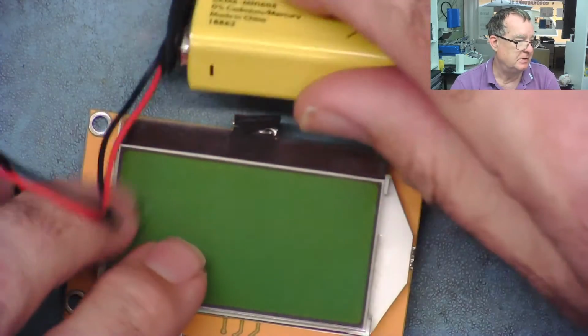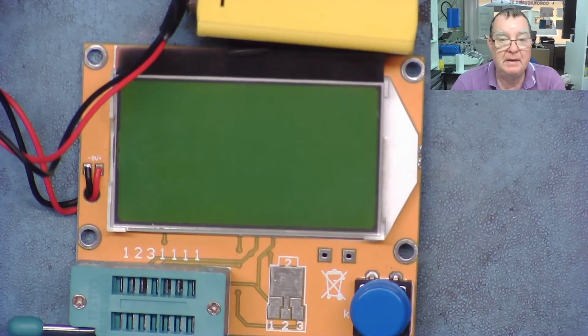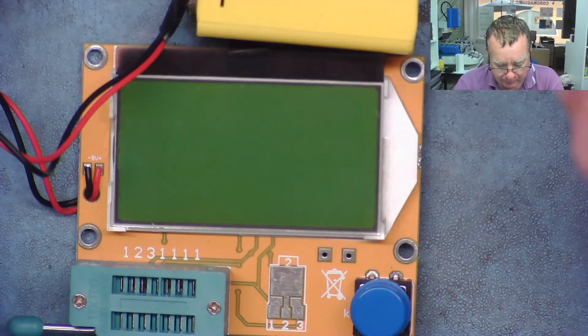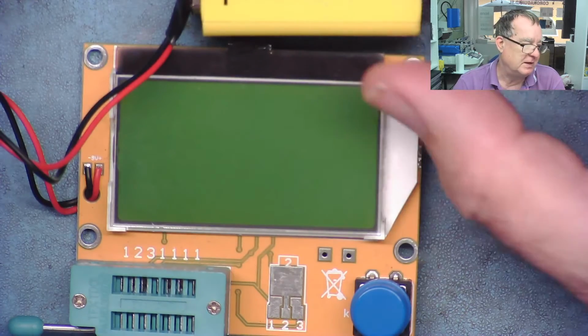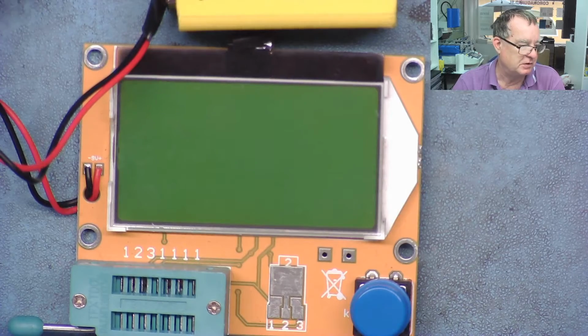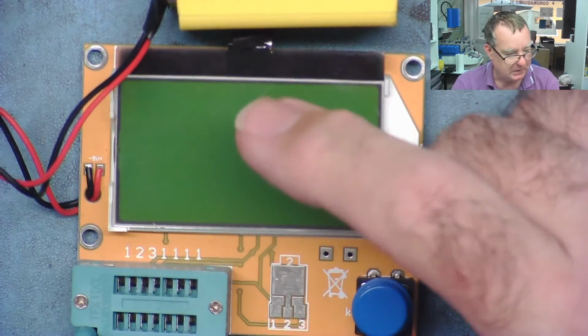So can we actually test an inductor with any of our meters? And the answer is yes, we can. One method we can use is an LCR meter. This is an inexpensive LCR meter and component analyzer I bought from AliExpress. It was about €6. It was very cheap. LCR stands for basically L is inductance, C is capacitance, R is resistance. So it means an inductor, capacitor, and resistance meter. And as I say, this also will analyse semiconductors.